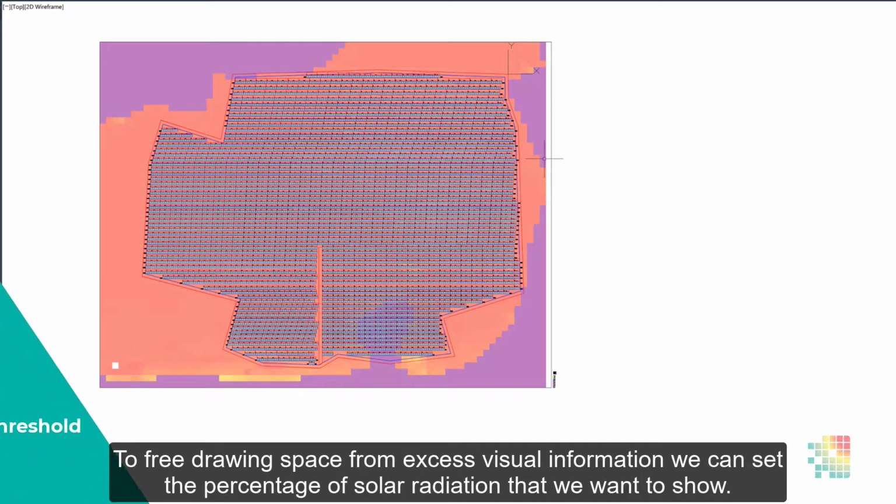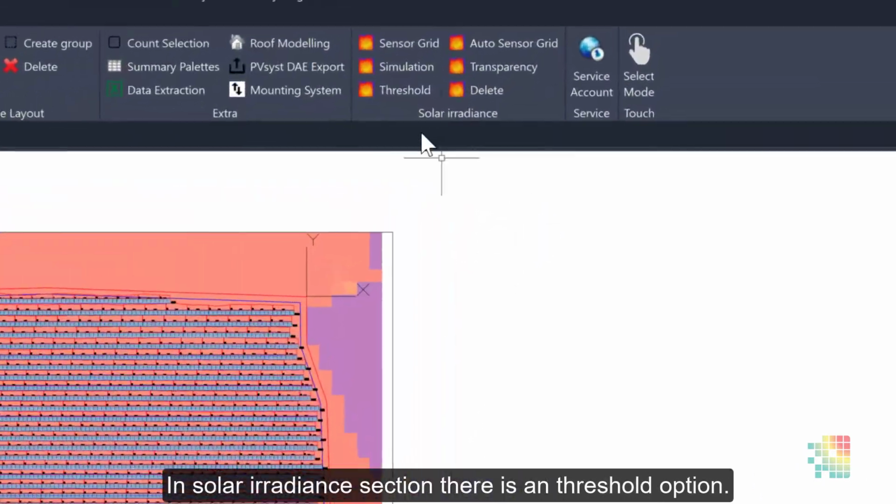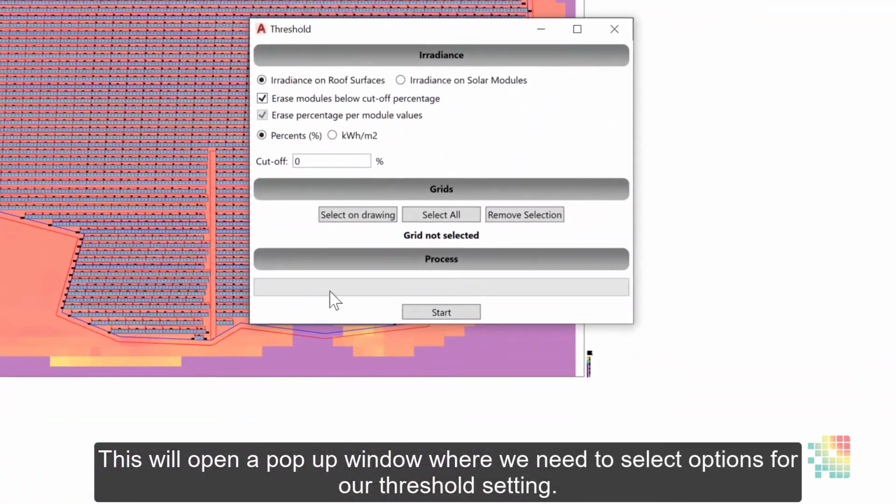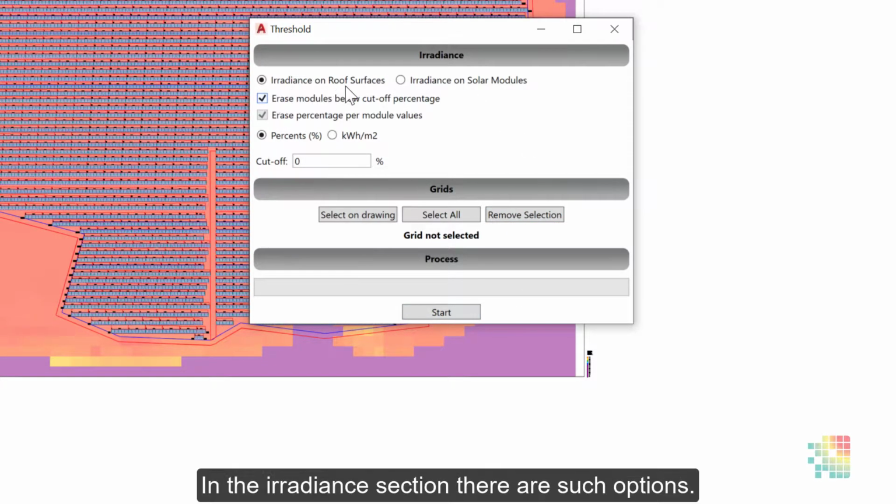To free drawing space from excess visual information, we can set the percentage of solar radiation that we want to show. In the Solar Irradiance section, there is a threshold option. This will open a pop-up window where we need to select options for our threshold setting. In the Irradiance section, there are such options.